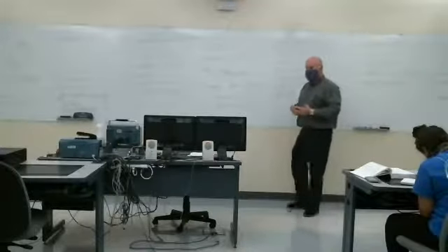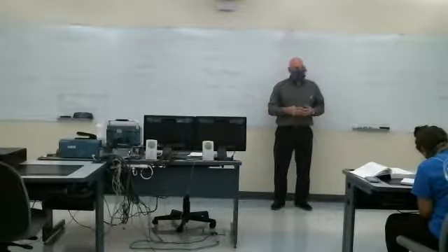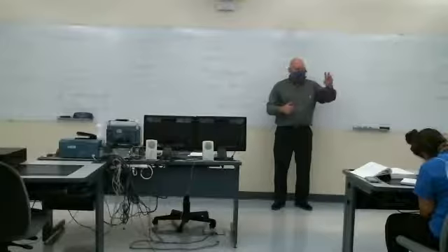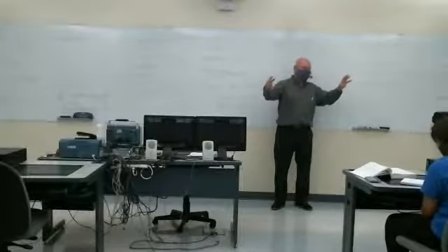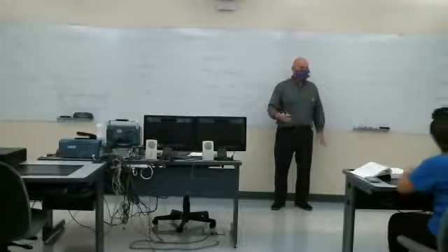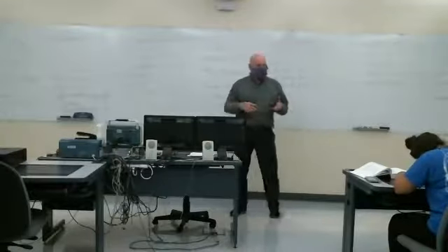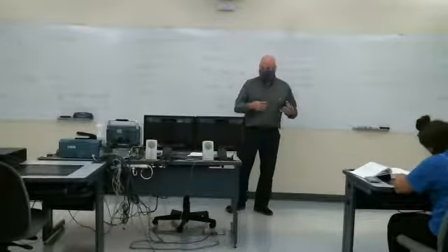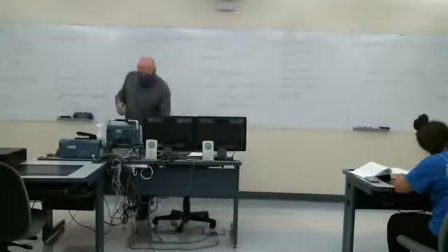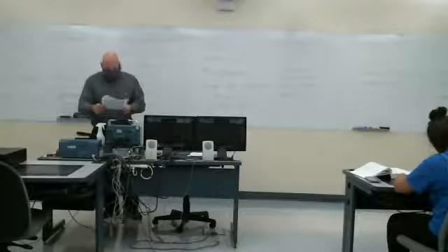Okay. Again, most of the systems we work with, we'll have these differential equations from our circuits that involve the R, L, and C. If the resistor was time varying, if the resistor is 1K this week and it's 2K next week, we're going to get a different output next week, right? But ideally, if the resistance and inductance values all stay the same, we should get the same output next week, just delayed by a week, to what we would get for that same input this week. So these can be a little head scratching as you work through these. So draw plenty of pictures.